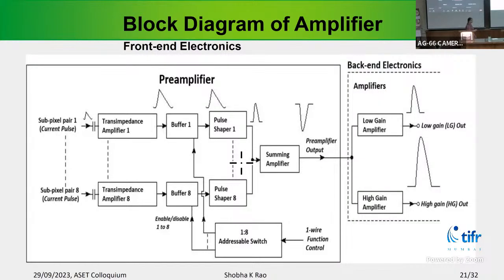Even changing the polarity. Polarity is changed because there is an inversion in that buffer. Non-inverting. See, because when you sum here, I'll show you. When you sum here, it is always better to sum in inverting mode, not in non-inverting mode. Okay, because in inverting mode of the op-amp, it's what we call